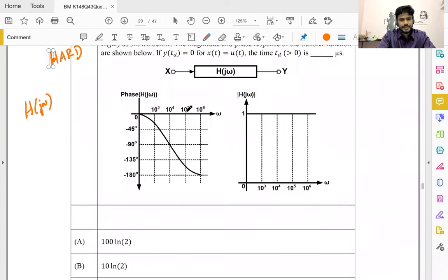So let's get here. When will the magnitude remain the same? And notice that for a first order system the phase is going to change by 90. There is one term, one pole or zero. If there are two things, perhaps things can change by 180. If things are conjugates, numerator and denominator, then the magnitude is going to remain 1.